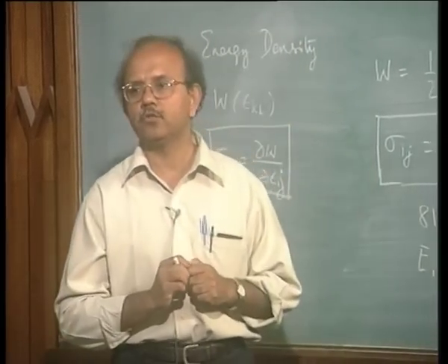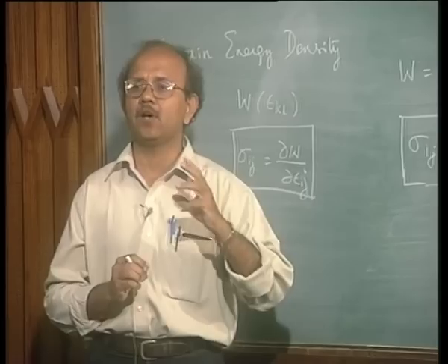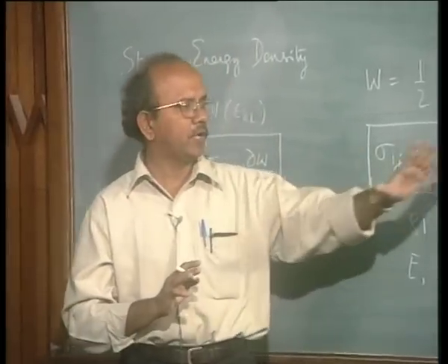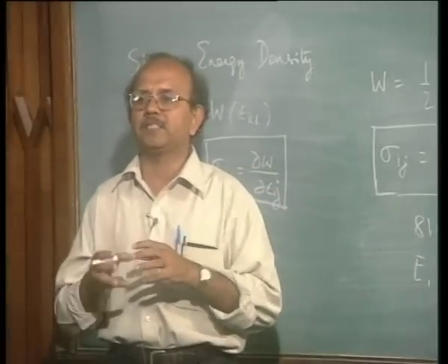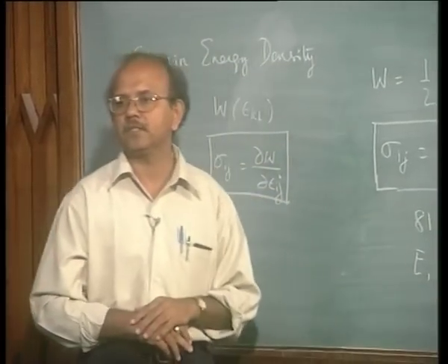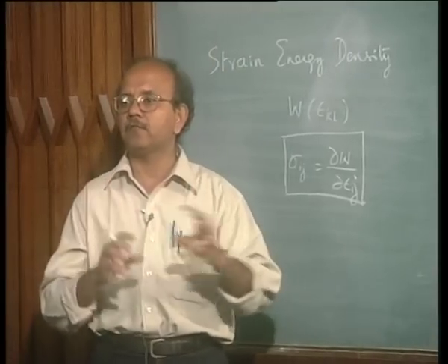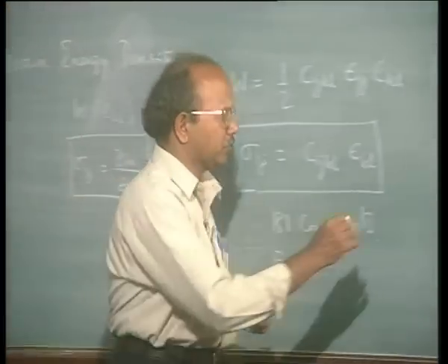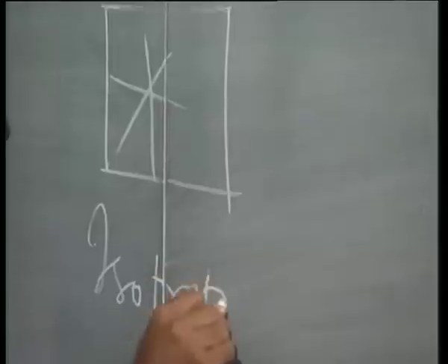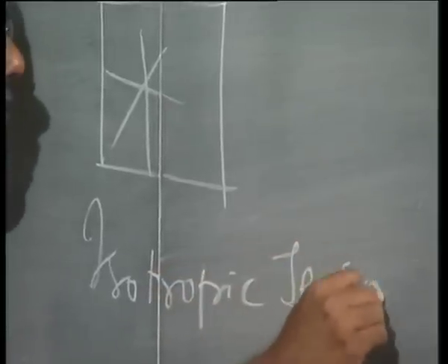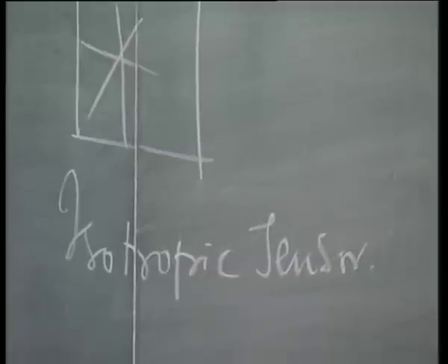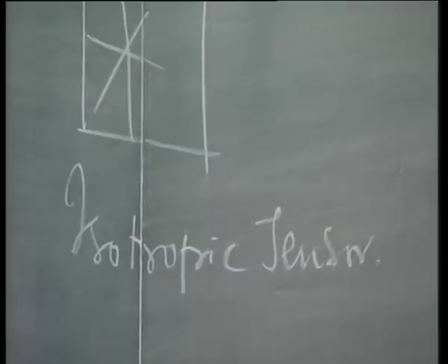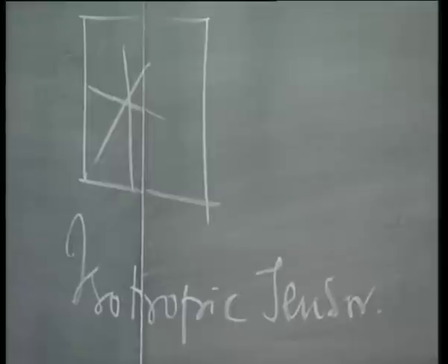What does this assumption give us? We signify this, or we put this mathematically. See how mathematics now plays into the picture. We say that if you are talking about an isotropic material, then I can put a subclass to this 4th order tensor. That subclass of this 4th order tensor is an isotropic tensor. Now, what is an isotropic tensor?